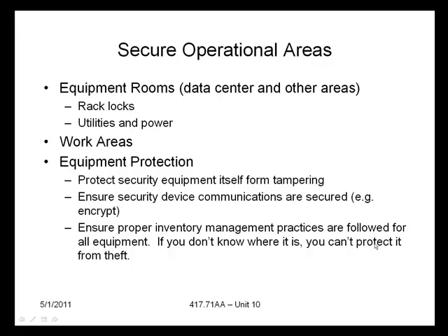You need to have some sort of alarm if a cable that is security critical is cut or no longer operative. If the coaxial, the old analog coax going to your old school CCTV is broken, you need to know that it's broken right away because that's an emergency situation. If you're using IP-based equipment, ensure that communications are secured and they're properly encrypted.